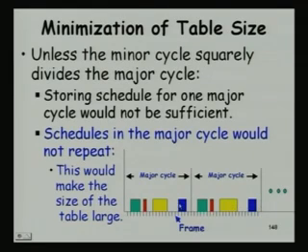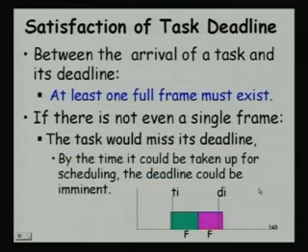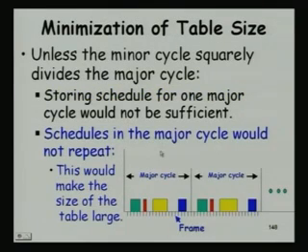until we have a lot of free cycles here, right. So, we cannot really repeat the schedule. Sir, yes, in the previous slide we have said that each frame should have a size that is a minimum of all task sizes. Okay. So, the first constraint that we mentioned, that the frame size should be at least as big as the task execution size. Here we have not drawn it like that, excepting I think the red one which is running here. So, this is not a realistic figure, just to explain this concept.